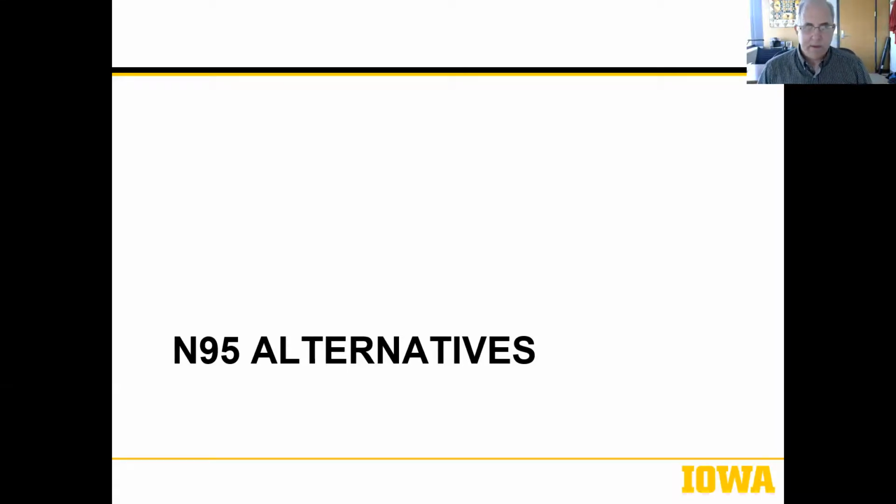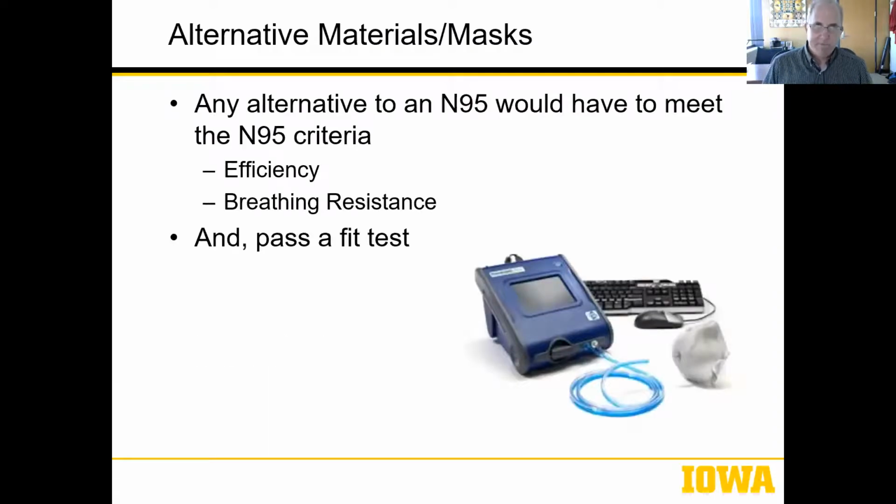So then the other possible avenue here is to go at alternatives to the N95 material, maybe kind of create your own. So in order to do that, we have to make sure that these fabricated or designed materials or respirators would meet the N95 criteria in both efficiency and breathing resistance, and pass this fit test. Does it form a good seal against your face?